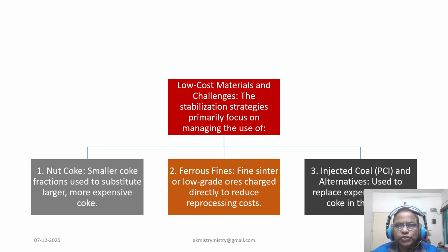of coarse coke. We use reducing agents like pulverized coal injection (PCI), oil, gas, or compatible waste to replace part of the coke charge at the top. When PCI injection rates are high, above 160 kg per ton of hot metal, maintaining nut coke level between 60 and 80 kg per ton of hot metal provided the best permeability and low thermal losses.